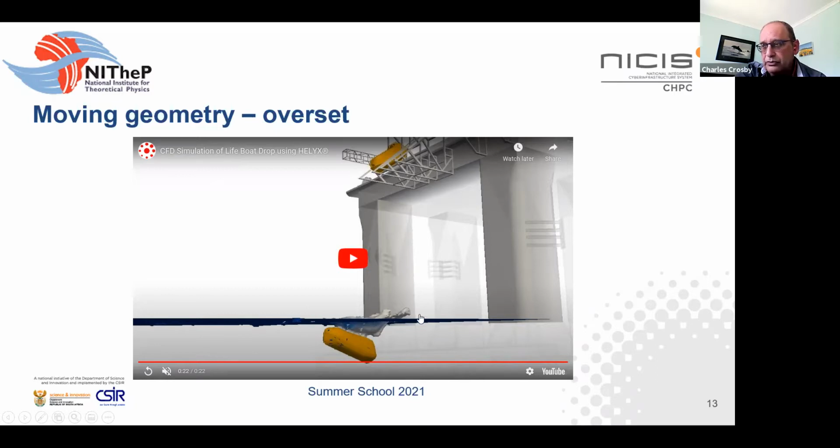The surface of the water is where basically you hit a 50% volume fraction of air or water, depending on which one you're thinking of. Mixtures of air and water are typically solved with a volume of fluid method. That's an extra transport equation, which basically works out your distribution of the volume fraction of water. So we can just take a look at it.